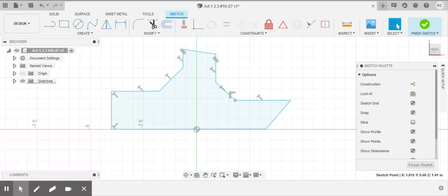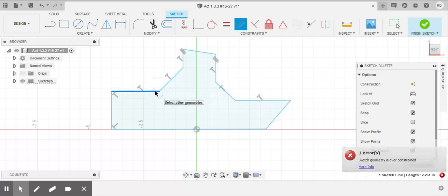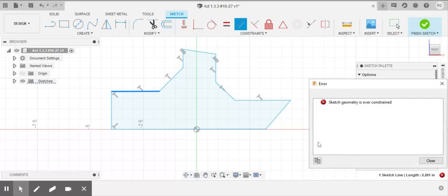It says to enforce a parallel line between 9 and 3. So they're saying make sure that this is parallel to that one. I suspect they already are because this is perpendicular to that and this is perpendicular to that, but we'll try to do that parallel. And we're asked to click on this line and those two. All right. So those two should be parallel. Oh, it says it's already over constrained, so it won't allow us to do that because it's already done, since we have enough perpendiculars there.